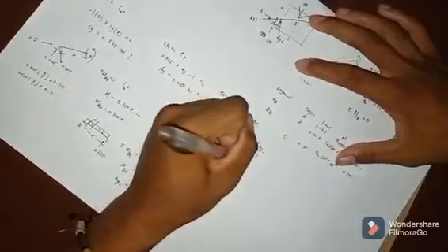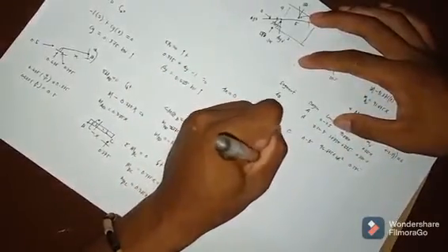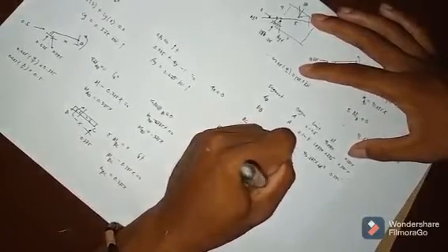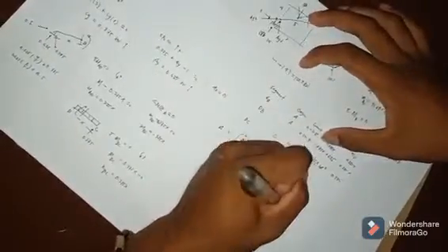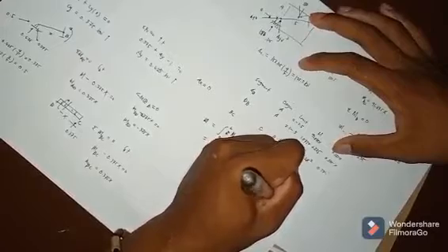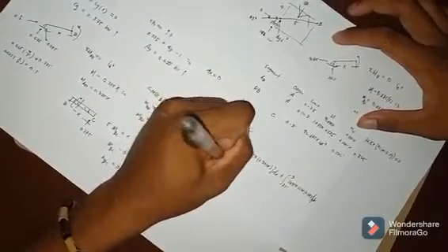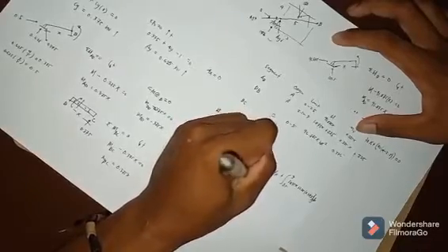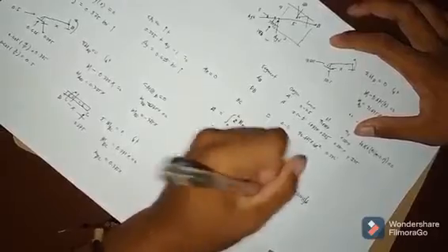So it is equal to 1 over EI times the integral with limits 0 to 2.5 of 91.875x times 0.375x dx, plus the integral with limits 2.5 to 5 of 1.875x plus 225 times 0.375x dx, and plus the integral of 0 to 5 of 96.875x plus 10 x squared times 0.375x dx.